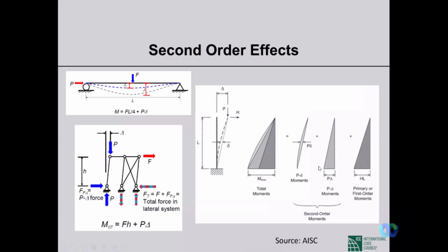Due to the application of these moments, and at the same time the vertical load and lateral load, the column as a member itself will bend, and that bending will cause a small delta moment that will not be at the bottom, it will be maximum at the mid-span of the member. So the shape will be something like this. You see the third sketch on the right side.